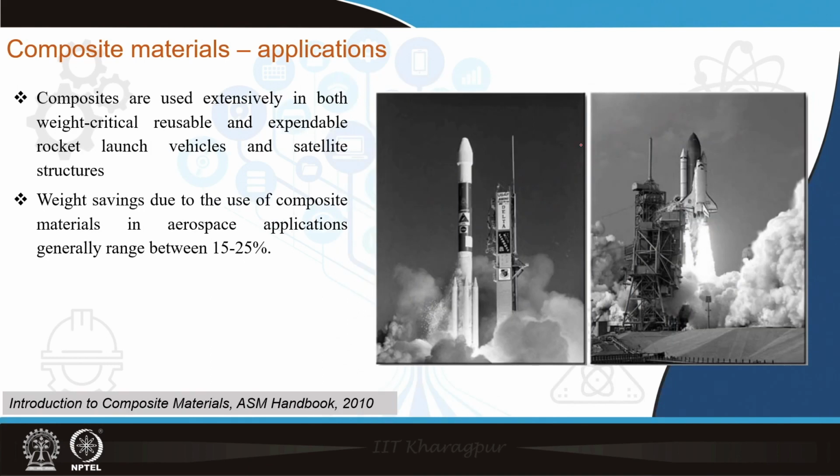Also for aerospace applications like rockets or supersonic aircraft, composites also play a very important role, because apart from their high stiffness and low density, composites also have good thermal properties. There are also other composites like some ceramic matrix composites, which have extremely high melting points, and by composite design the ceramic matrix composite can also increase the fracture toughness over the bulk monolithic ceramic, and this way these ceramic composite tiles are excellent materials for protection of the metallic chassis of these aircraft components.